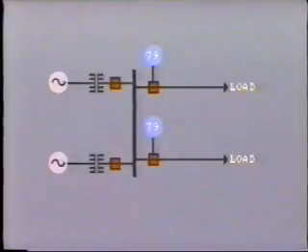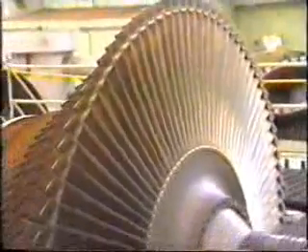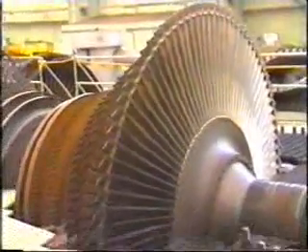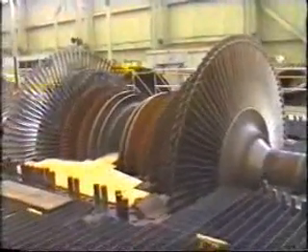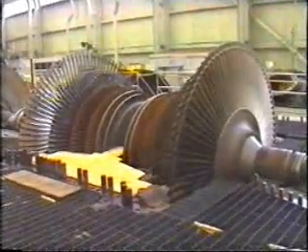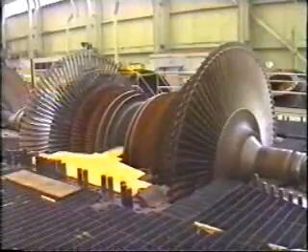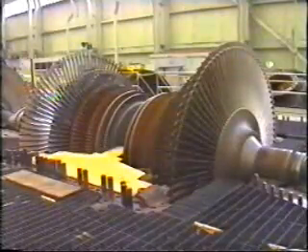The shock to the generator of suddenly rejecting load, then applying load again, could conceivably cause mechanical stress and ultimate damage to the turbine and generator rotors. For these reasons, and to preserve system stability, instantaneous reclosing relays are usually not installed at locations close to a generator. We can see that the application of reclosing relays depends upon the system location and the specific system.